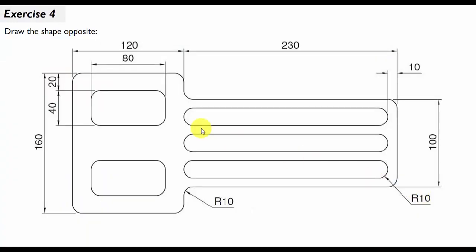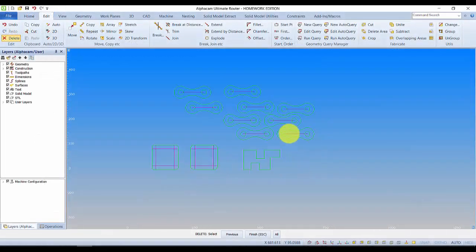And here is our next exercise. Now pause the screen and take note of the measurements, or download the file on Learn Online, which will have those dimensions. But you can see it's largely based on squares and rectangles with a number of fillets applied. So I want to begin drawing that over here.